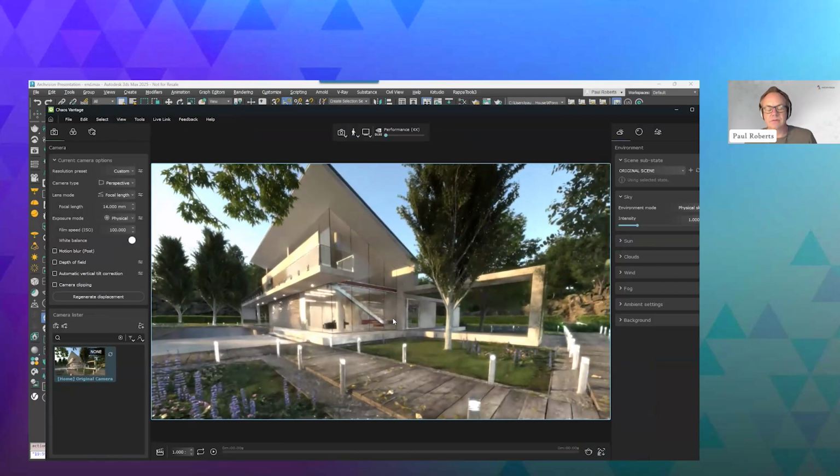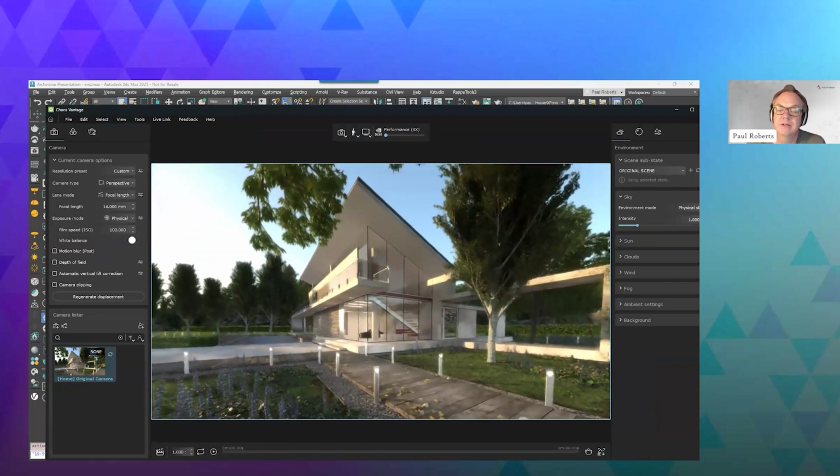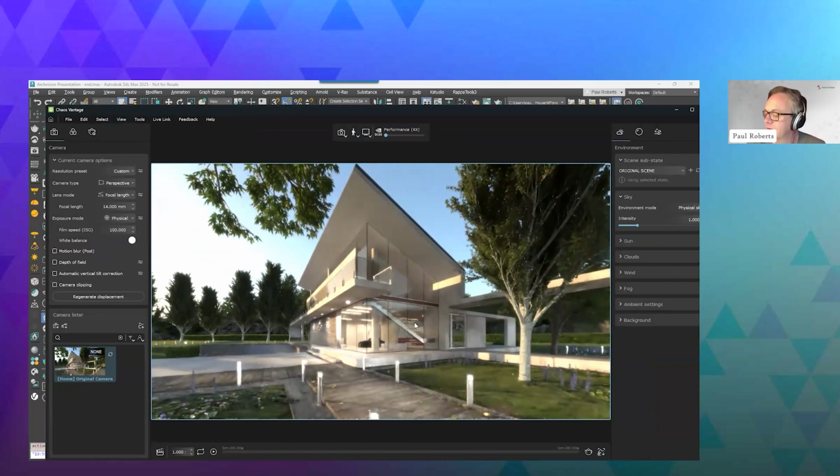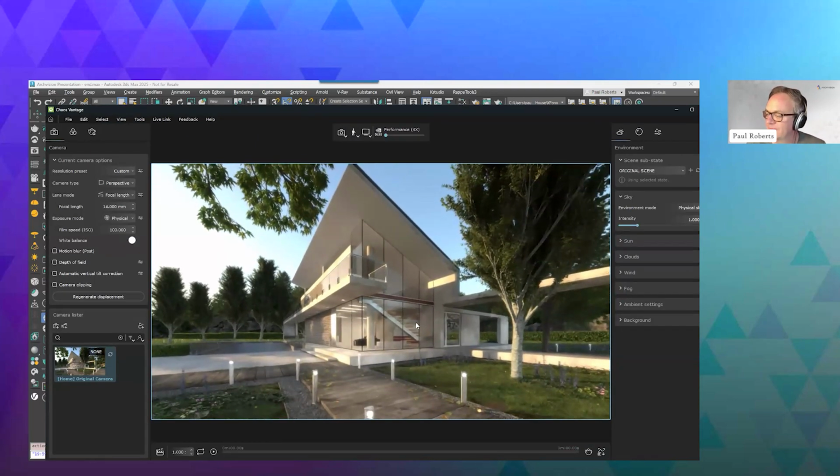Some plugins support us rather than we support them, if you see what I mean. It just depends whether they're locked down or not. Another piece of software that supports us is Unreal. The Datasmith plugin natively exports ForestPack and RailClone to Unreal without you having to convert it to native instances first. So you can just leave those as they are and do a Datasmith export, and it all should just work, hopefully.